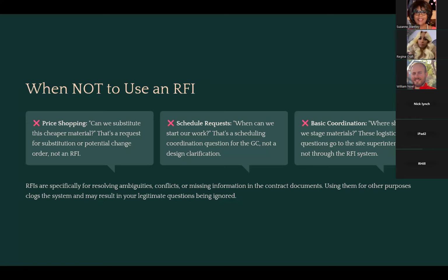General contractors love subcontractors who write RFIs, but they want them to be about things that RFIs should be about and not these type of things. So yeah, they specifically revolve around conflicts and ambiguous topics in the contract documents. Anything outside of that is not an RFI.